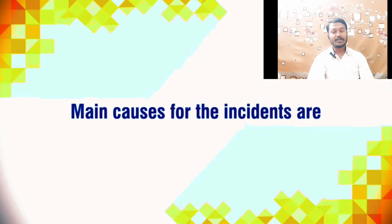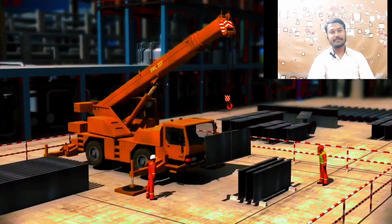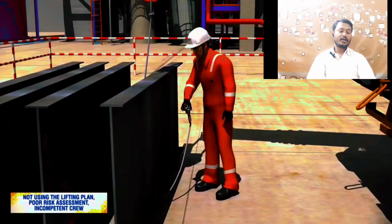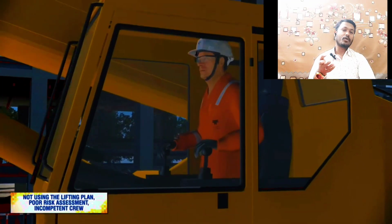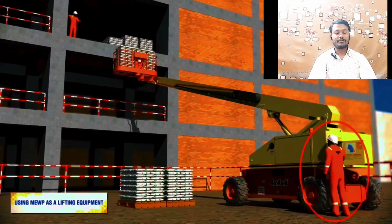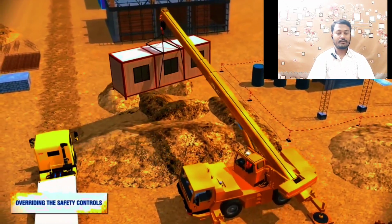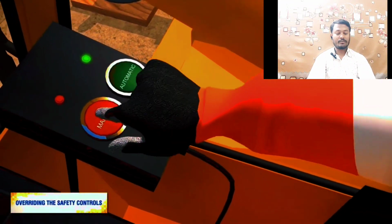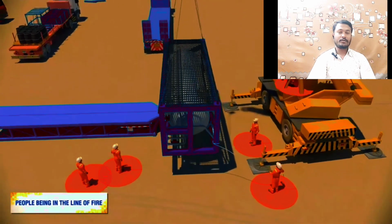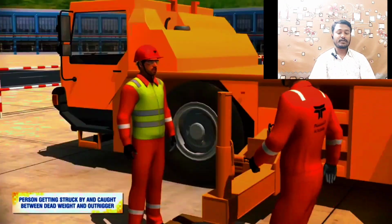Main causes for the incidents are defective wire rope sling, violation of the set procedures such as not using the lifting plan, poor risk assessment, incompetent crew, using MEWP as a lifting equipment, overriding the safety controls on the lifting equipment, people being in the line of fire,